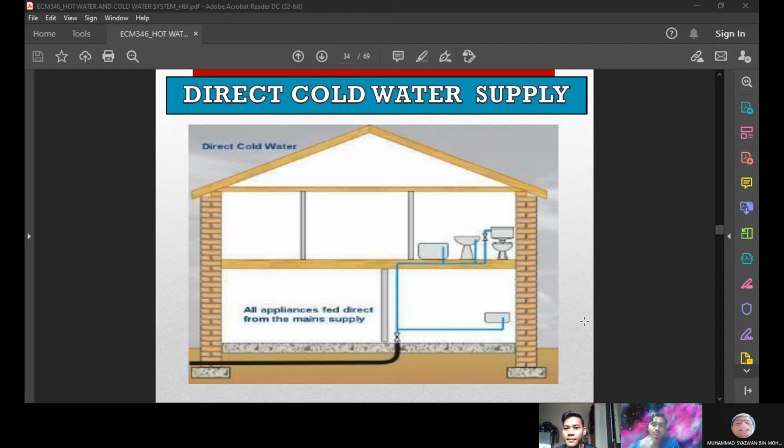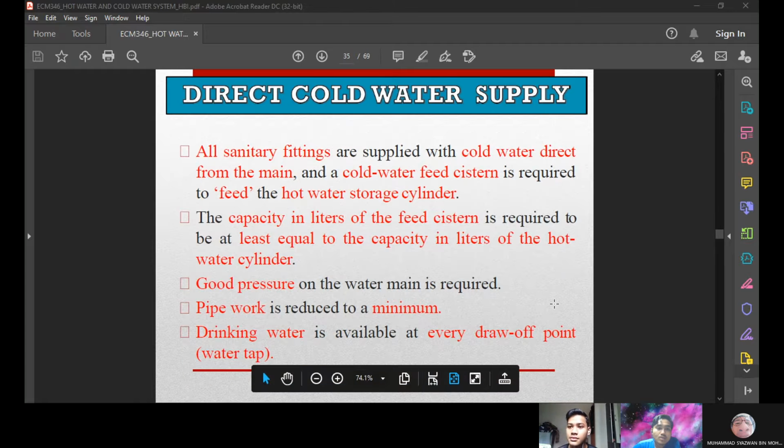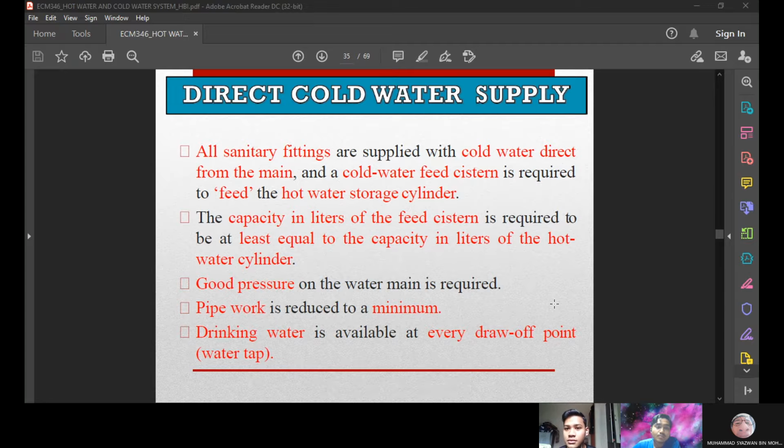Okay, I will introduce the cold water supply. A cold water supply system comprises a myriad of pipes that deliver water to taps, appliances, firefighting equipment, and wherever else it is needed. The design itself must conform to accepted engineering practice as well as all relevant building and plumbing codes. All water service pipes must be the size that is suitable for the quantity of water delivered, as well as the pressure required in the relevant plumbing code.